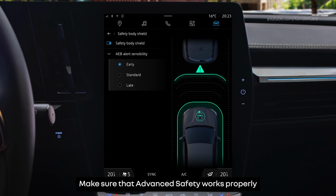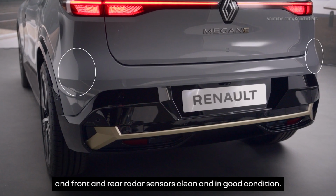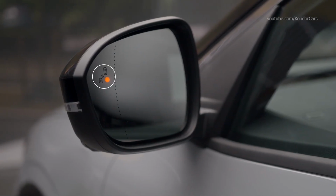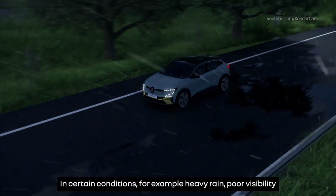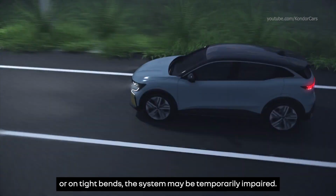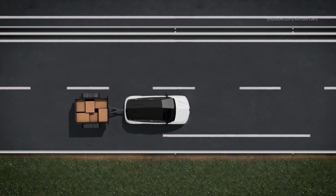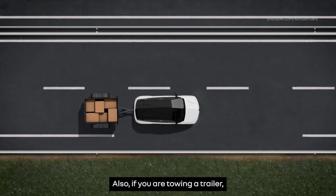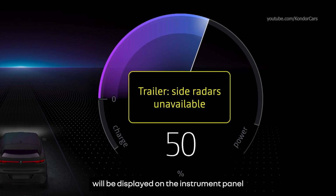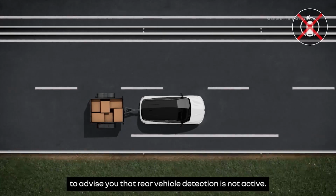Make sure that advanced safety works properly by keeping the camera, rear view mirrors, and front and rear radar sensors clean and in good condition. In certain conditions, for example heavy rain, poor visibility, or on tight bends, the system may be temporarily impaired. Also, if you're towing a trailer, the message "Trailer Side Radar Unavailable" will be displayed on the instrument panel to advise you that rear vehicle detection is not active.